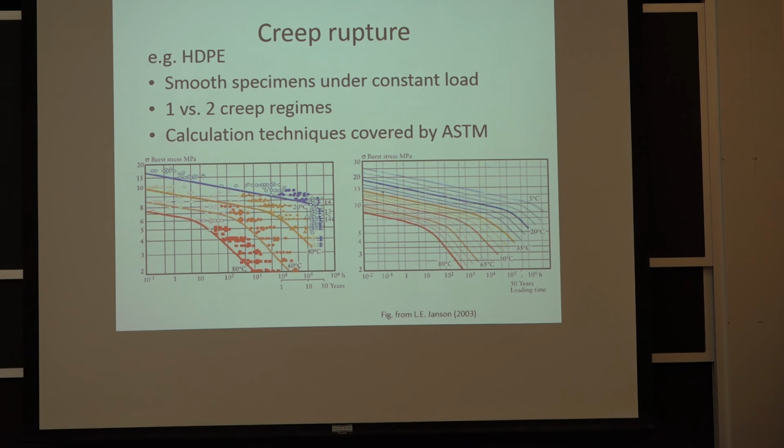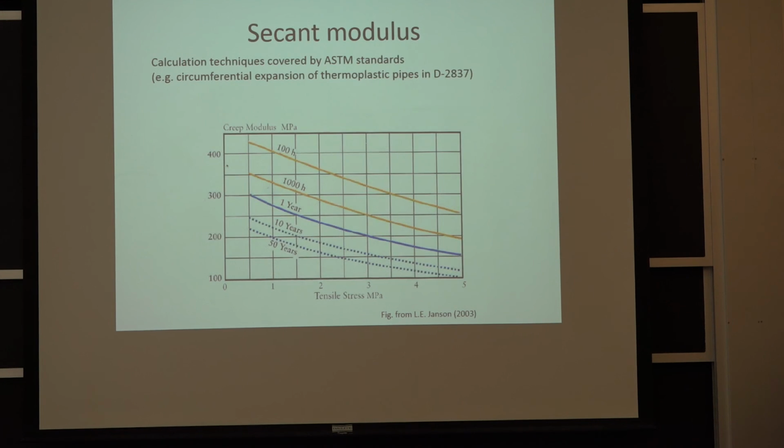If you try to do it really quick, if you heat up too much, a lot of times you change the phenomena of deformation. And so that's where there's always a limit in the accelerated testing. I'm sure you've heard of time-temperature equivalence and all those sorts of things, and I'm actually not going to spend a lot of time on that, but I do want you to remember, if somebody says, oh yeah, I'll let you know if this plastic's going to be good for 50 years.